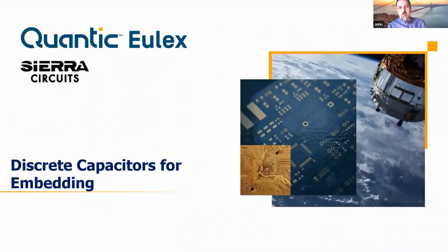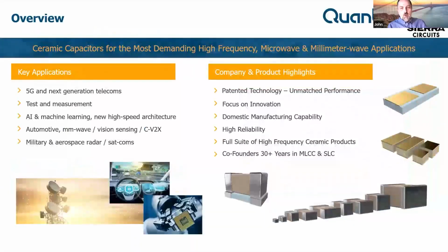So sometimes the capacitance of these planes, like for decoupling, the planar capacitors of 1 mil are perfectly fine. But sometimes, like in a MEMS device or some of these other things, the capacitance density of these formed capacitors is not enough. So you may need to boost that. And we have a sister company called Ulix, and they just came up in the last couple of years with a patented type of capacitor, they call it a gap capacitor. And what it does is it makes it much easier to incorporate a discrete embedded capacitor.